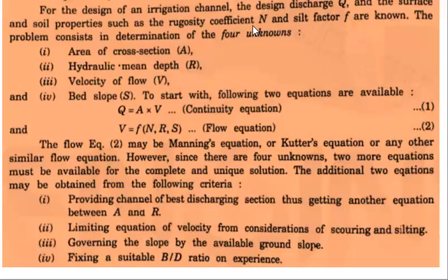Even the roughness which is caused by the ripples formed on the bed of the canal, right? And also I hope that you remember about the material and the value of n, the material for earth, masonry, and concrete. The n value varies according to the material. So again, if you wish, you can check out the older notes and the lectures which I have given you in the last class, and also I hope that you know about the silt factor.